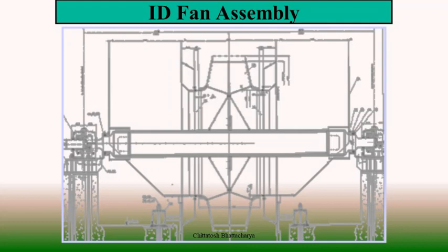The shaft is free to move through this non-driving end bearing. So this is also called a non-located bearing. The motor side bearing is called a located bearing, and it is fixed in position.